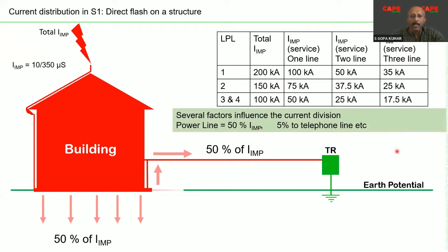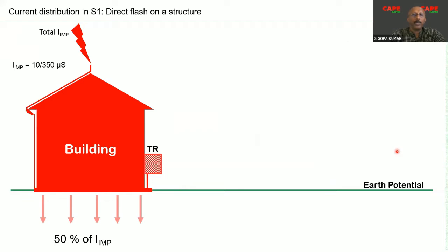This is the thumb rule which is always used. You also should understand that in large buildings, for example industrial buildings, or nowadays commercial multi-storied buildings, the transformer is always a part of the building, inside the building. And under this condition, if the equipotential bonding is properly made along with the neutral earthing and the body earthing of the transformer,